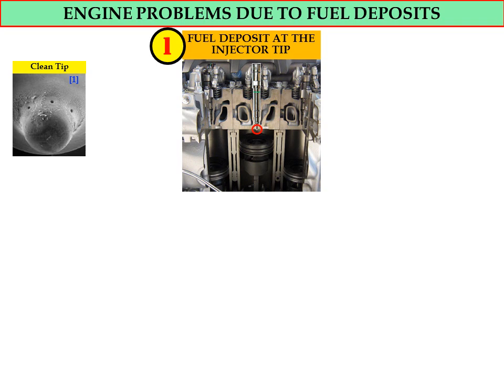Now we want to show the difference between the clean injector tips and the injector tip that is already covered with fuel deposit. Figure 1 shows the clean tips. We can see very tiny holes of the injector tips, where the diffuse spray will come out from these holes.